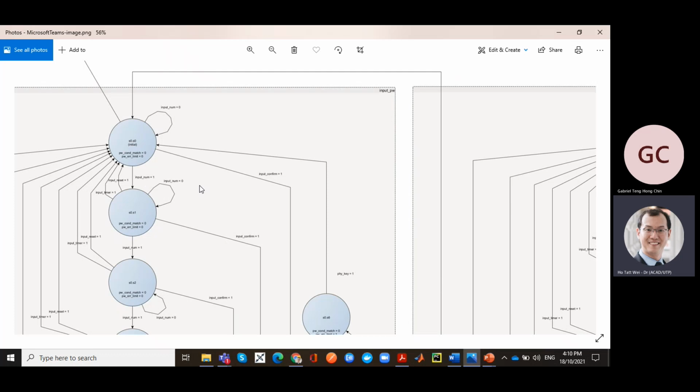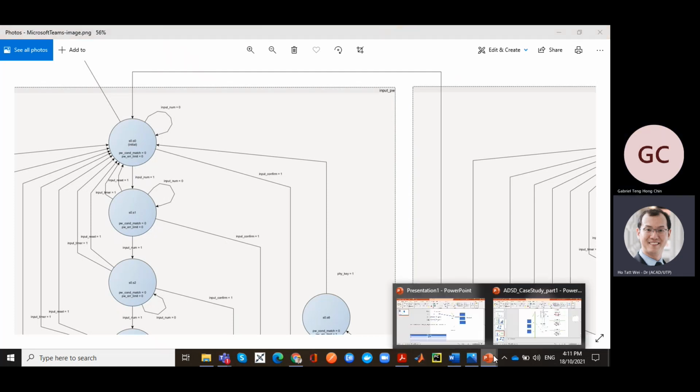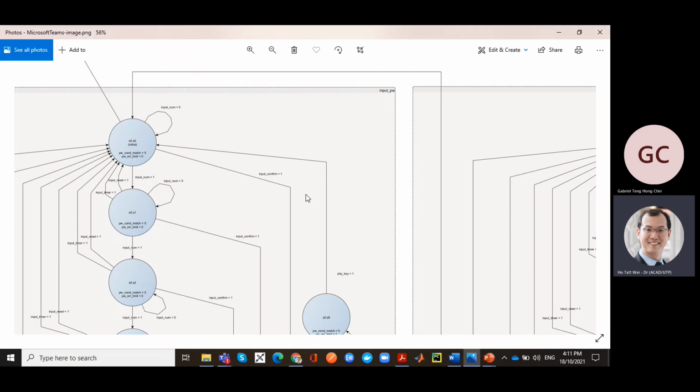So I'm going to go ahead and say maybe input reset is the priority. My order of priority of the bits, I can actually just say order priority. I hope you understand: if this one does not mean the rest are don't care, because if here you say don't care, then you have an overlapping situation in these 2 arrows. So you must specify an order of priority. If you say this one is 1 and everything is don't care, that means here input confirm has to be 0, and so on and so forth. Can you follow?